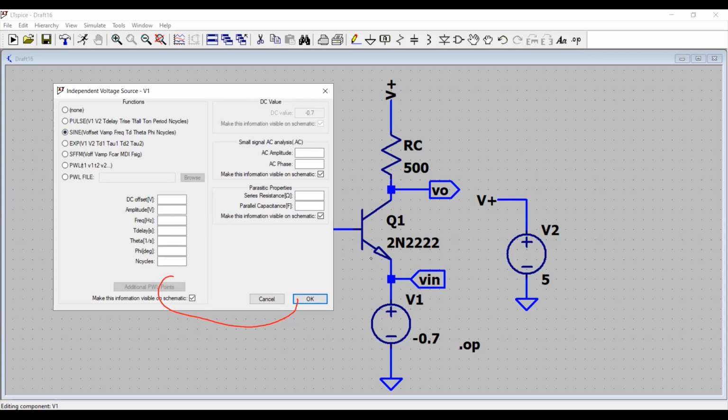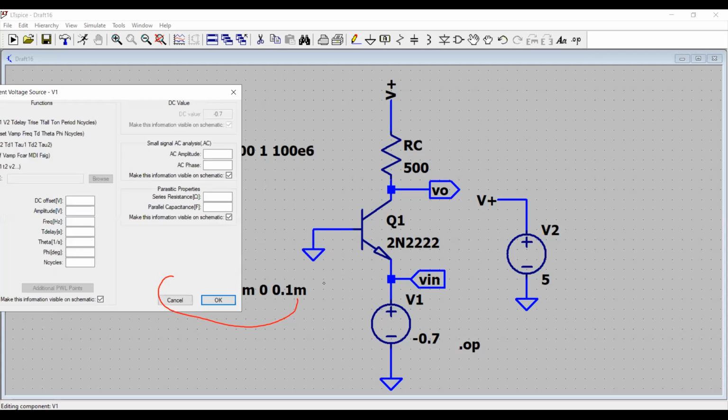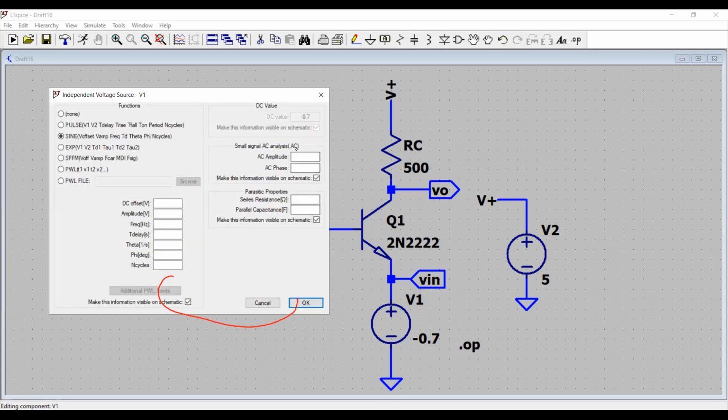Yes, I need that because otherwise I need to use some external resistors to provide the biasing to the transistor to make the transistor operate in an active region. I haven't used the biasing network here. So just for the analysis, I need to keep it. So DC offset can also be used for that, because the DC offset will also work like that. So I don't use that.